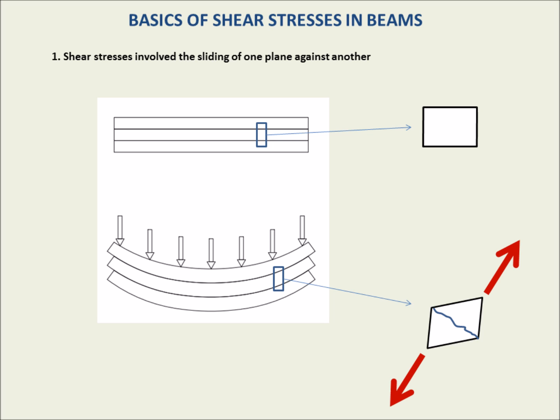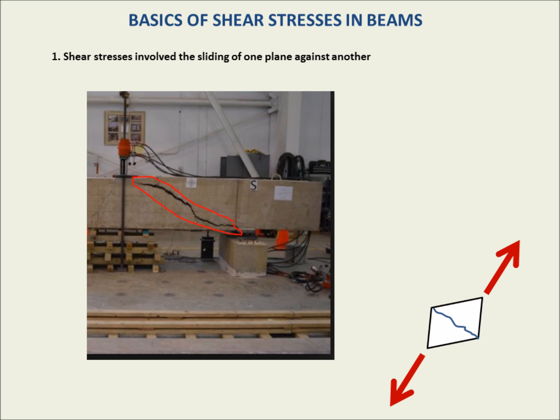Hence, in brittle materials that don't have a lot of elasticity or will not continue to ductilely deform in the plastic region, but that will brittlely fail in tension. In such materials, an example being concrete, we can clearly observe this 45-degree failure mode, or failure plane, I should say, in the shear failure mode, right?